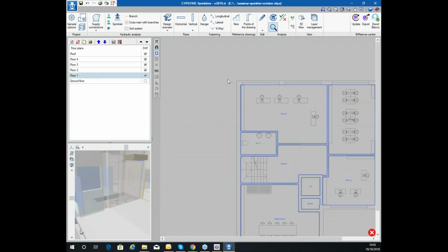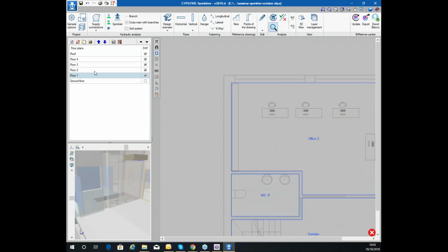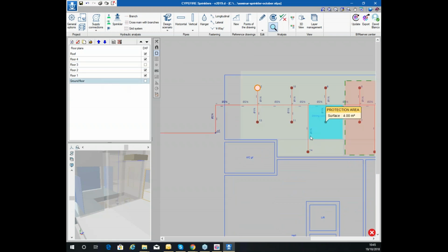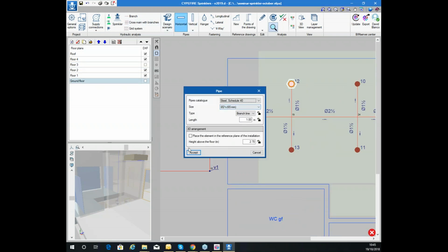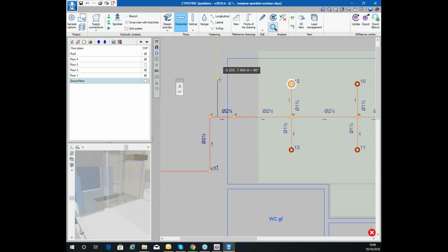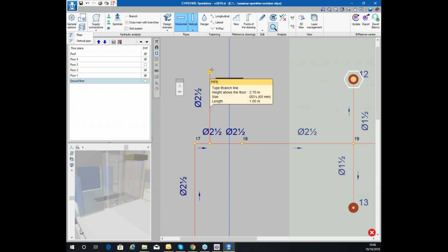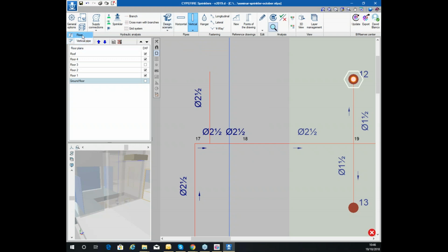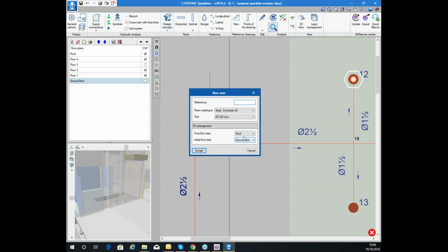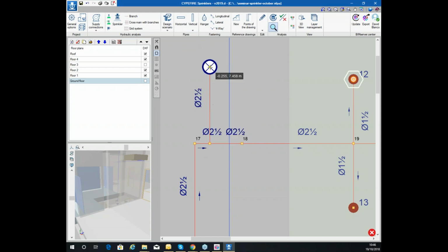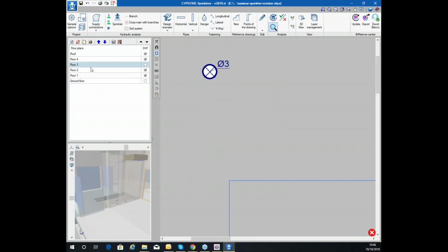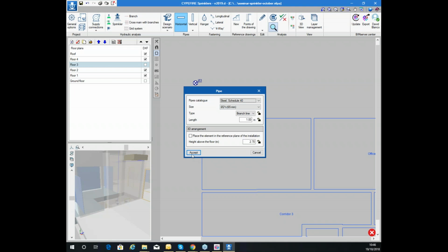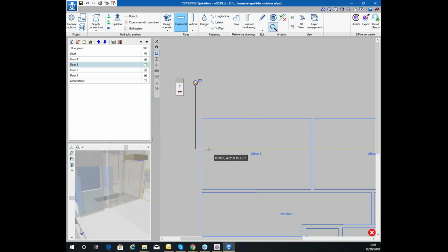Okay. So, well, we could add, for example, the design for different floors. I can show you, for example, floor 3. From the ground floor, I can establish a horizontal pipe here, and I can connect from here to a vertical pipe. Okay. A vertical riser from the ground floor just to floor 3. So if we move to floor 3, I will see here the riser, and I can connect a branch and horizontal pipe just up to here and up to here.